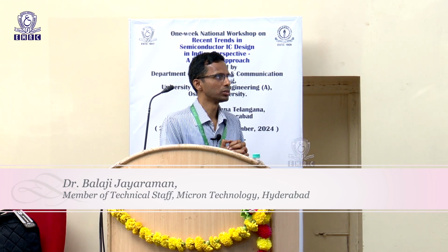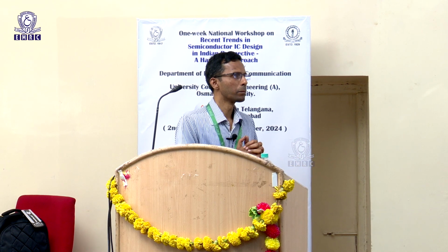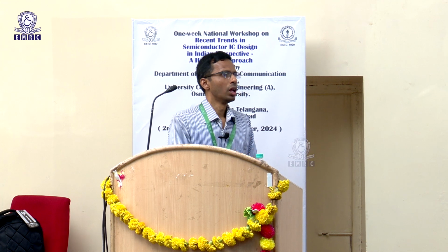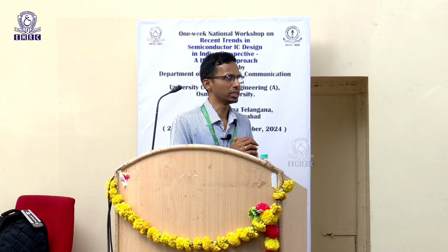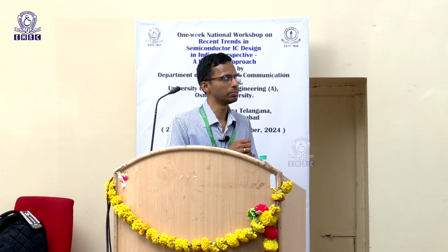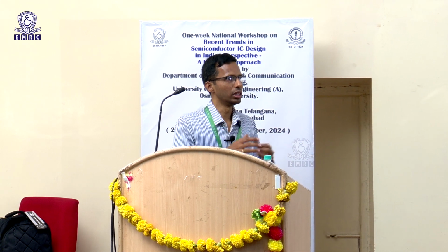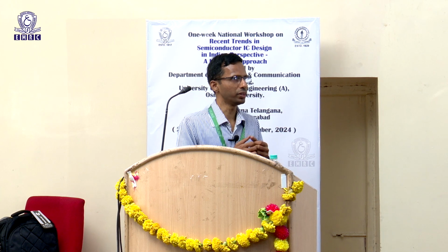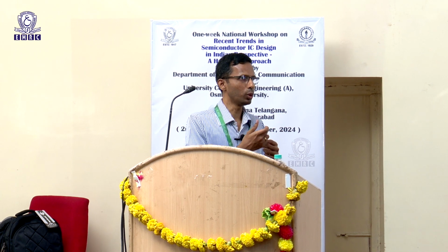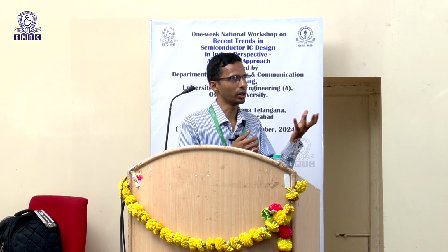Okay. Is there any analog portion in SRAM? Analog portion in SRAM, again, if you are using two different supplies for your core versus your periphery, to realize that additional core supply, you would need a bandgap voltage reference and a voltage regulator. So that's an analog supply.